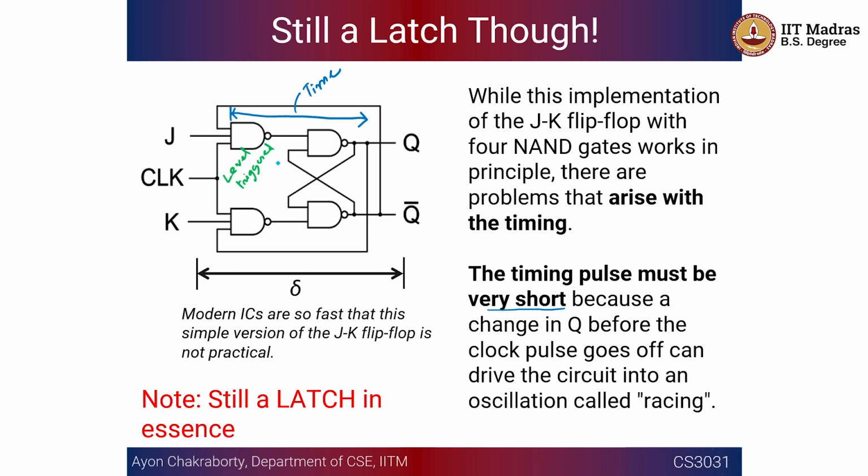This is called active low or active high, right? Which is basically high, same thing. But remember that the amount of time the clock is going to be high is the same as the amount of time the latch is also going to be on, which is not the case in case of an edge triggered circuit, which is a flip-flop.